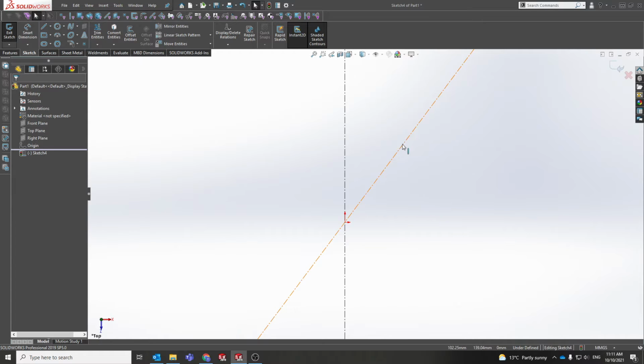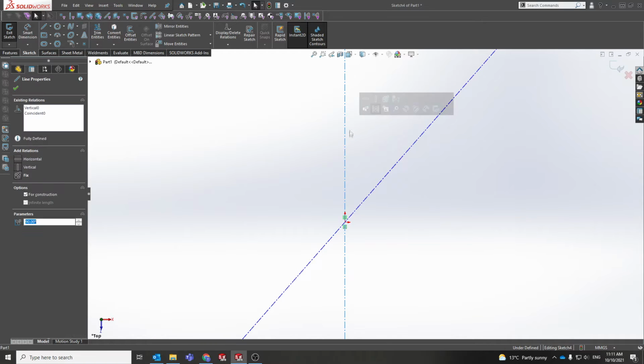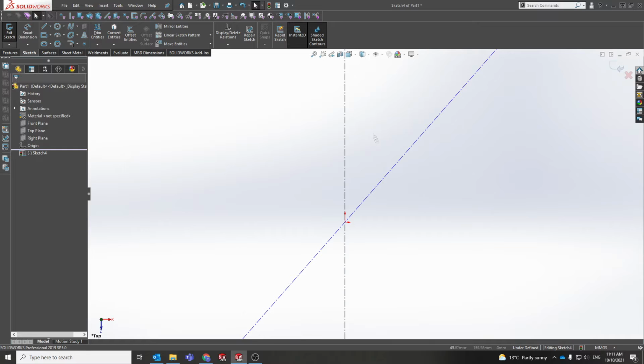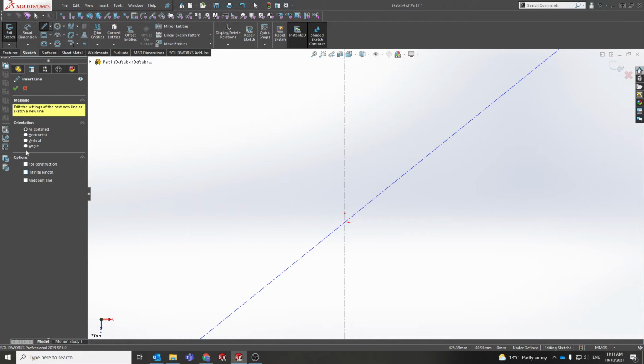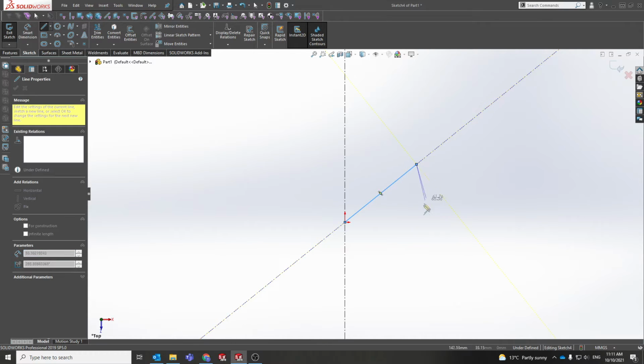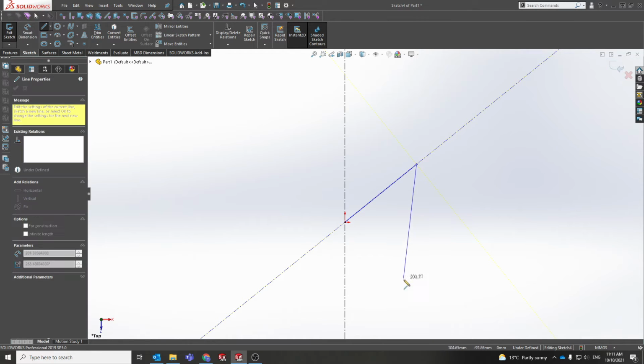So now if I click on this and I drag it, it actually moves. Whereas this line, because it's actually got a vertical constraint on it, which locked itself in when I was laying it down, it's locked in there, right? It's not moving anywhere. But this line is. So if I go to draw a line on there, so I go just a regular line. Let's say I want a triangle. Let's do something that gets mirrored. So we'll go down a bit further.